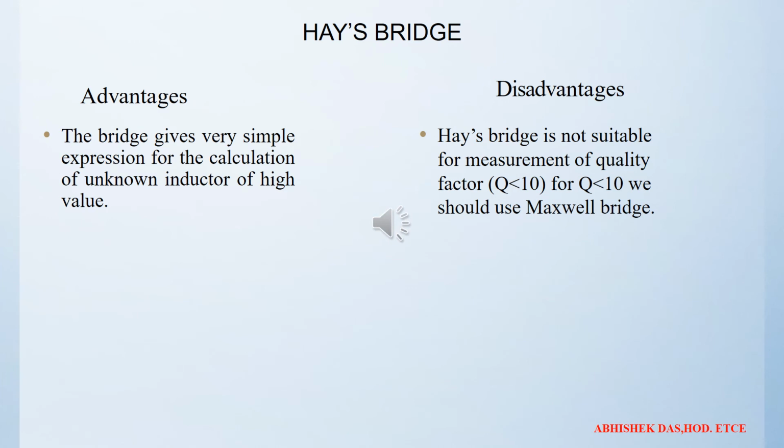The advantage of the Hay bridge: the bridge gives a very simple expression for the calculation of an unknown inductor of high value. The main disadvantage of the Hay bridge is that it is not suitable for measurement of quality factor less than 10.